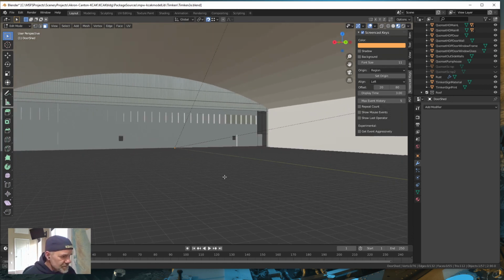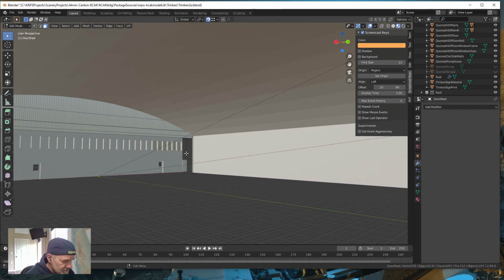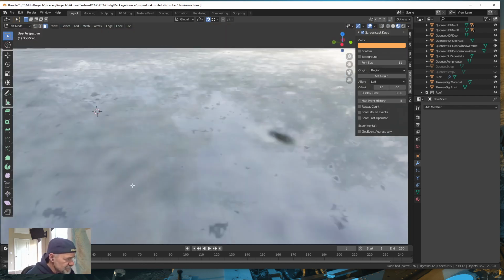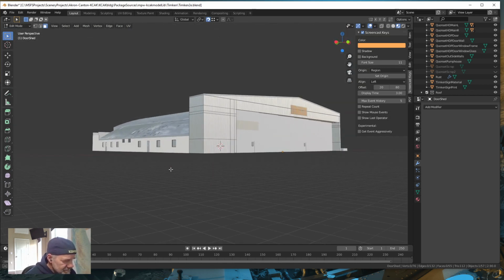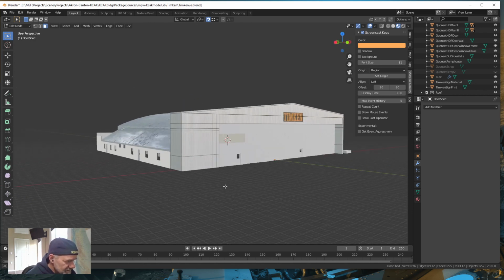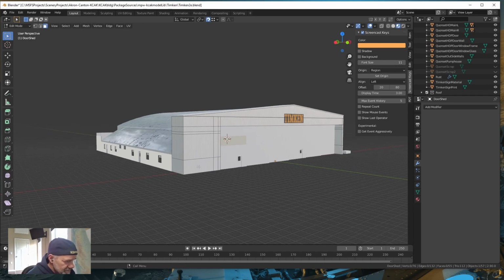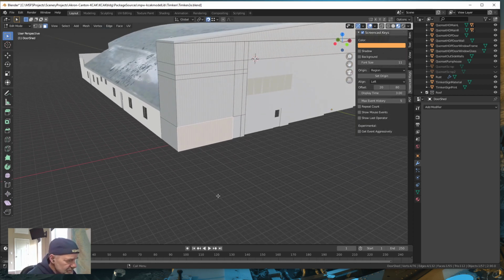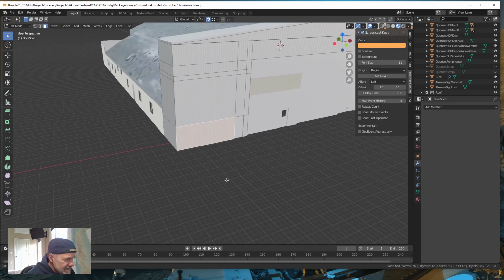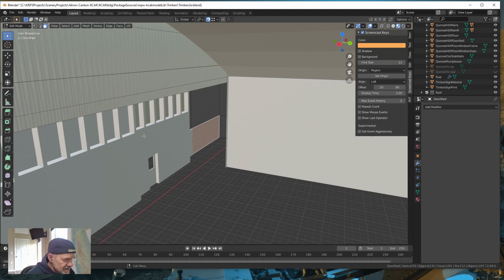Okay, now remember I was talking about fixing some textures. Notice how right here we're transparent. Okay, that's because this is a PBR texture applied to our outside face right here, this wall right here. And since the normals are pointing out, the PBR texture gets applied to that direction. But I'm going to select this polygon, focus on it, with the period on the number pad. Now, since that's a PBR texture, it gets applied to the outside.